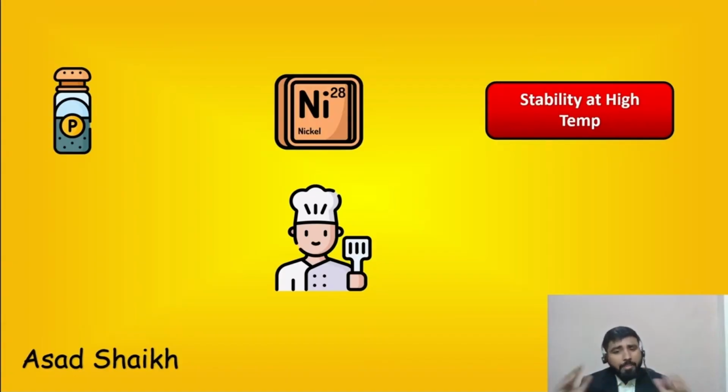So for most applications, you will see SS316 being good, but that does not mean every single application. If your fluid is okay, if the piping material is carbon steel, if high temperatures are not there, corrosion is not going to be there, then I prefer to go with the carbon steel body. You will save a lot of cost.